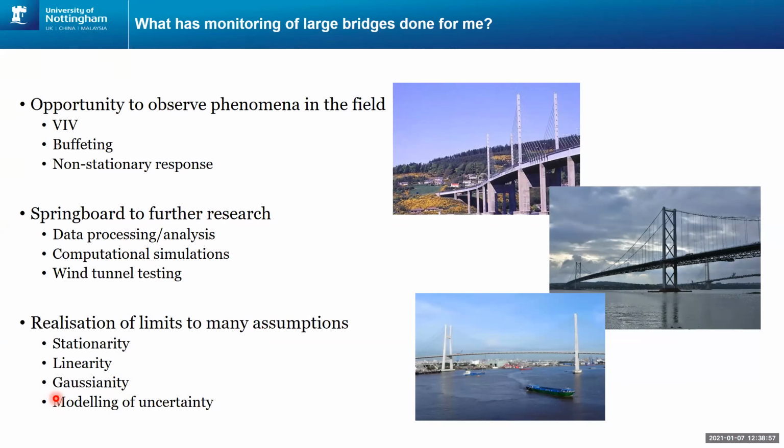It's been a springboard to further research, especially in terms of data processing, data analysis, computational simulations, and wind tunnel testing. And it's also exposed, I think, limits to many of the assumptions that are made in the analysis and design of these structures, such as stationarity, linearity, the assumption that the process is Gaussian, and the modeling of uncertainty.